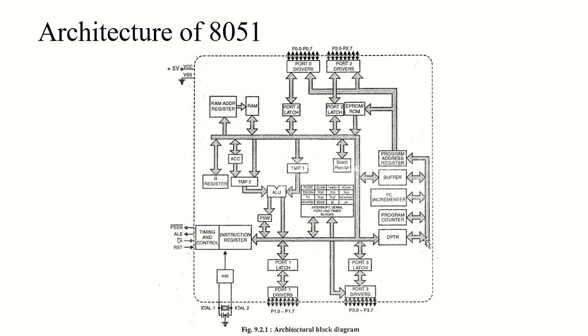This register can be accessed separately as lower 8 bits and higher 8 bits, so it can be used as a 16-bit register or two independent 8-bit registers, right? So always remember, the data pointer is a 16-bit register.